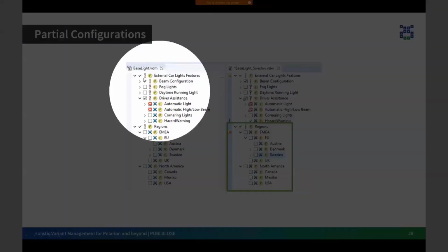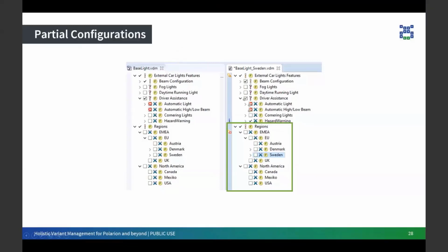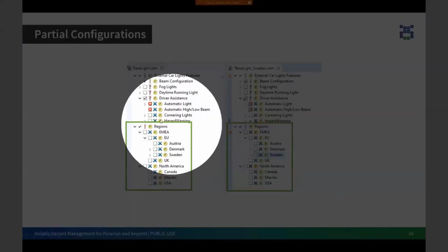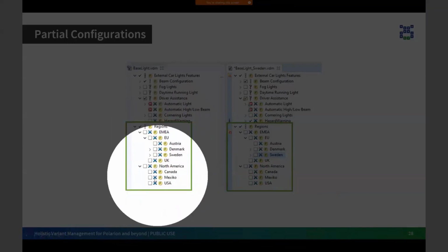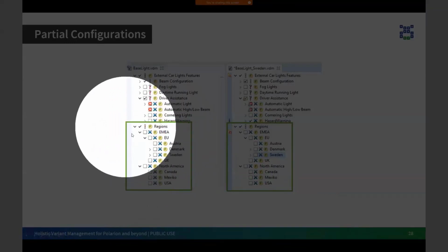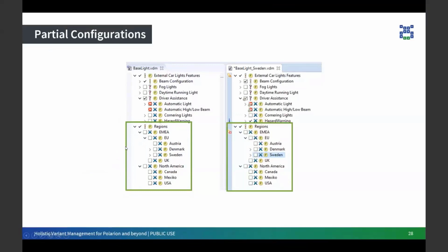If you tell pure::variants, however, that this is a partial configuration, pure::variants doesn't throw an error marker in this case, as it knows leaving the decision open here might be on purpose, so that you can do this in the next step with the actual variant that inherits from that partial one. And if you need this inheritance concept, this stepwise configuration, not only on feature model side, but also on solution side, so if you also want to generate out of a 150% set of Polarion assets, 120%, out of which in the next step 100% are generated, then partial configuration also has you covered.